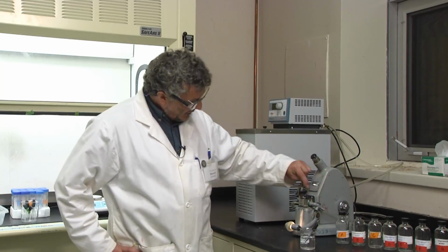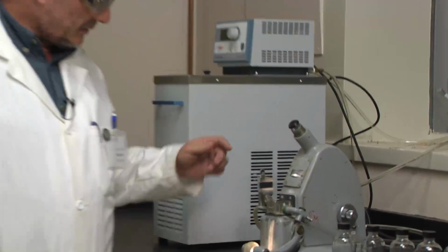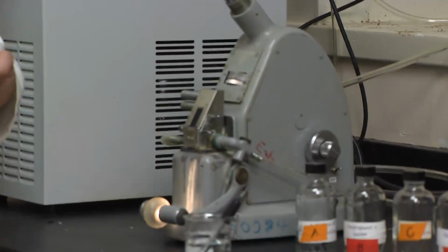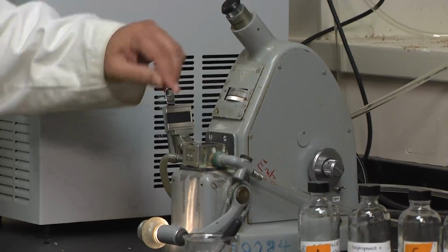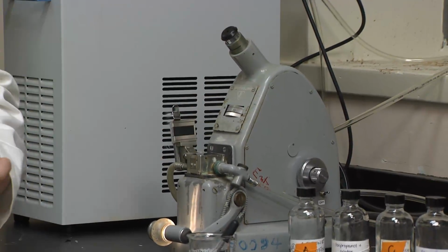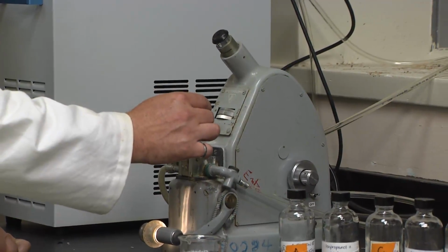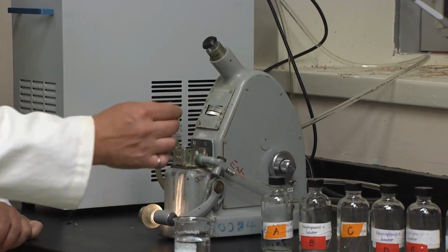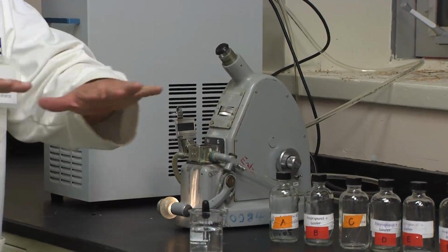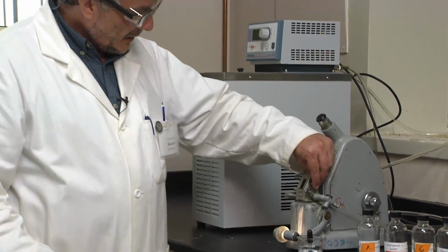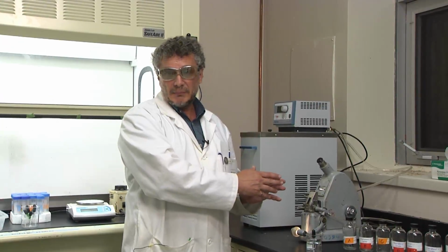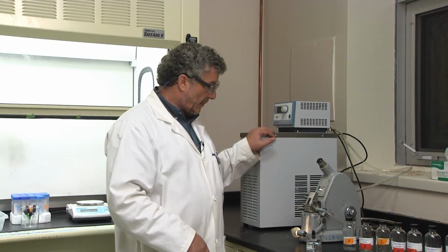The refractometer opens here like that, very simple to open, no force required, and will close in the same way. There's a tiny gap between the surface of this prism and the one down here, very, very small. So all we want to do is place a couple of droplets in here, and then once we close the prism, it will spread the droplet all over the surface. And after we close it, it will very quickly equilibrate to the temperature of the refractometer. So it doesn't really matter at what temperature we pick the sample. All the samples will be read at the temperature of the refractometer, which is now controlled by the bath.